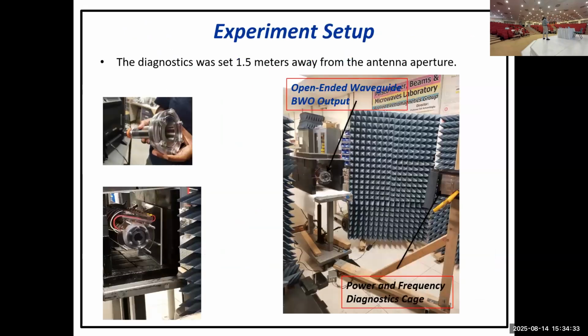Okay, this is the dispersion curve. Now we have everything tested in cold test. We're ready for hot test, to put it under vacuum and high voltage experiment. But the problem is not just to have your source and start firing and collect data. How to collect data? Diagnostics is a whole field. You need to work weeks, maybe months, to calibrate your diagnostic setup.